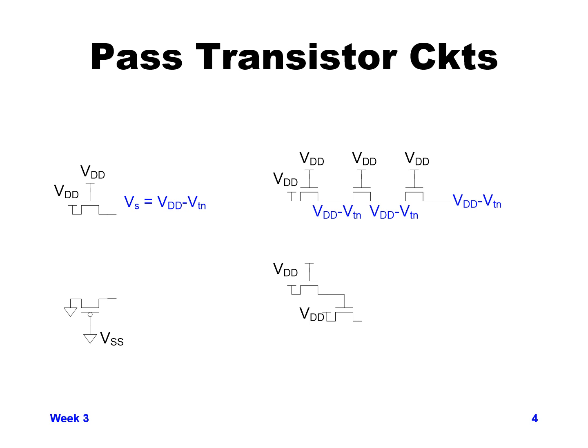And again, for the third one, it will also go up to VDD minus VT. So you will get VDD minus VT out of each of them because it's dependent on the gate to source threshold voltage. Since the gate is all the way at VDD, the output source can go to VDD minus VT.